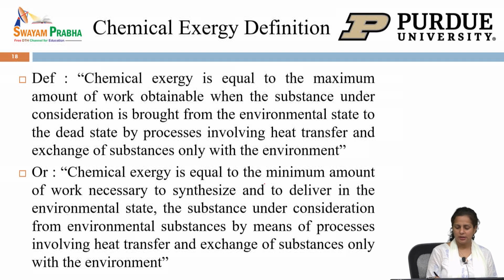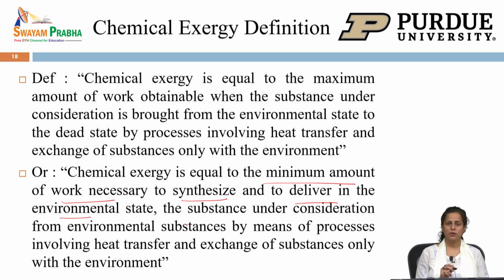It is equal to the minimum amount of work that is necessary to synthesize and to deliver in the environmental state. So, what you are doing is that you are bringing material from the dead state, which is complete thermal and chemical equilibrium in the environment. You are synthesizing material and bringing it to the environmental state, and you do some work in that process, and that work that you do is the exergy of that material.